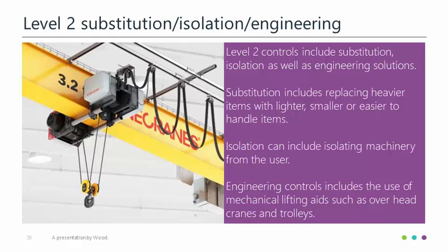If you do use tools and equipment, remember to use the most ergonomically suitable tool where possible, and make sure that you have an inspection and maintenance program set up as well. It will be challenging to have suitable equipment if it doesn't continue to operate and function as intended, as you are just introducing another risk, when the actual aim is to reduce your hazardous risks. Make sure that the equipment is the right equipment for the load and the work being done. Checking the weight lift limits is important.